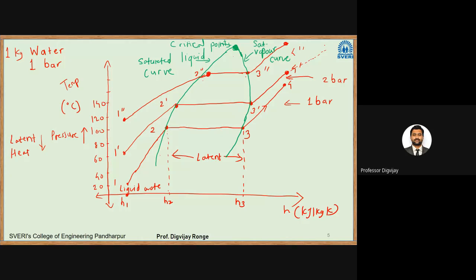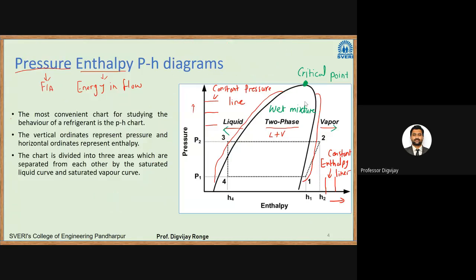What happens in general is the enthalpy increases. So here maybe we have got some enthalpy, maybe H4, and that enthalpy will increase. The interesting thing here is the critical point. So what happens at the critical point? No latent heat is added. If you increase the temperature of water at 22 megapascal, what happens? No latent heat is required. That liquid is converted directly into steam.